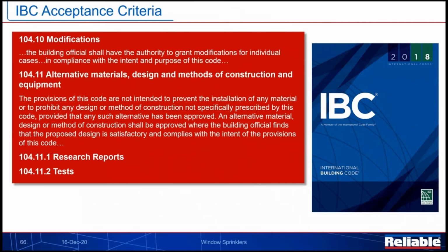Well, that's the area that a lot of people like to turn to when you get into trouble with a building or a sprinkler system, and that's the part that talks about how do you build something outside of what's in these documents, and that's basically where it says that with proper validation, with new products that come on market, that you can do it. You can go beyond what's written in building codes or in NFPA 13. And really, it is a well-validated process.